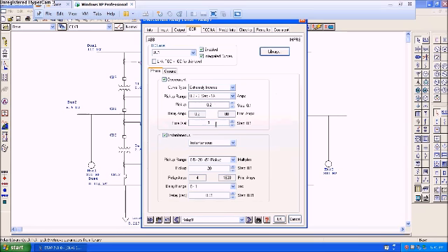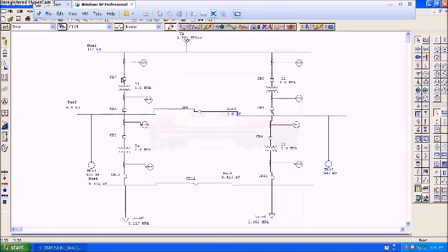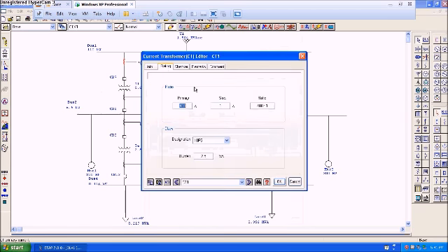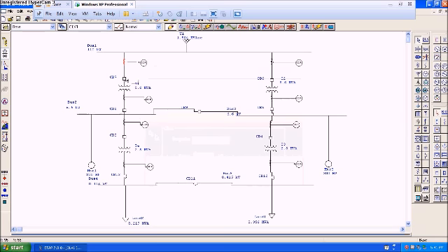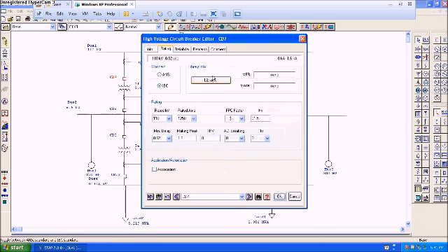You can see the currents which are flowing in the circuits are red in color. Now we will create a fault. Though we can create a fault anywhere in the circuit, for the purpose of showing we will create it here, near relay 6. Now if a fault current is here, then relay 6 will definitely operate first, then relay 5 will operate, and then relay 7 will operate, which we can see through a curve.